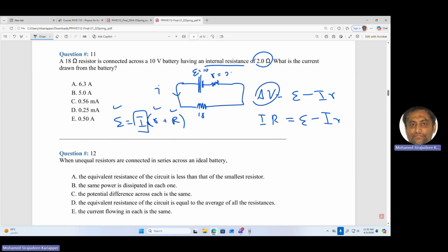Sometimes it can get confused with the question, because sometimes the question will give you the open circuit voltage without giving the load resistance, and you will take this equation and you will be looking up and down. It didn't give me, how can I find the resistance, right? So that is why you need to know what we mean by the open circuit voltage.